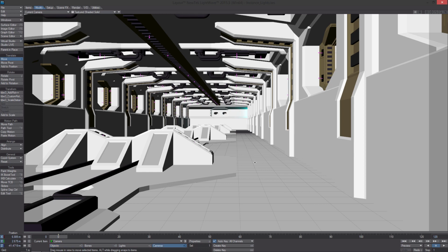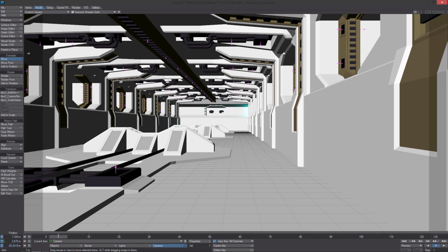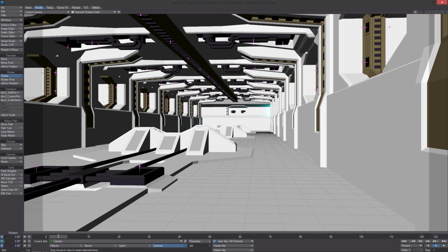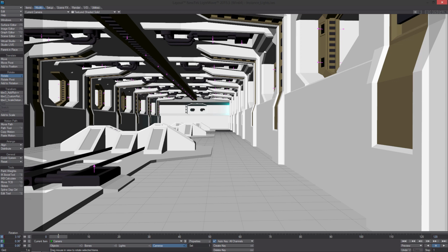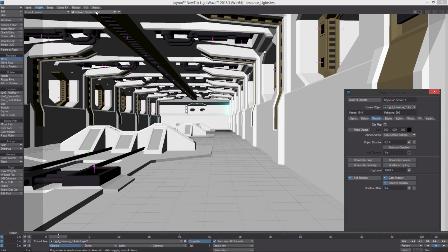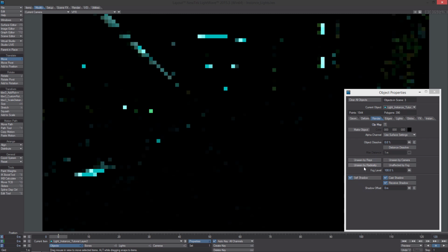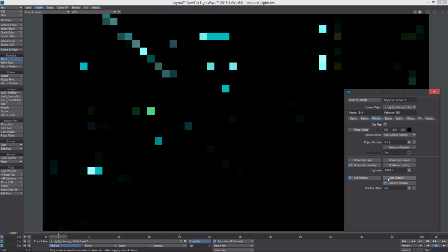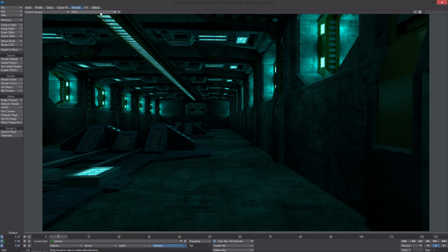So now I just loaded that other geometry in. That was the lights themselves, the luminous geometry. And I moved the camera up. So now there's luminous geometry where the lights are. The lights are sitting a little bit behind it. So the only thing we have to do here is, you'll notice when I go into VPR, you won't get anything. So what we want is, we don't want that luminous geometry to be seen by radiosity, because it's not necessary because there's lights there, and we don't want it to cast a shadow. I let that go for a good bit, just so you can see how it cleans up.